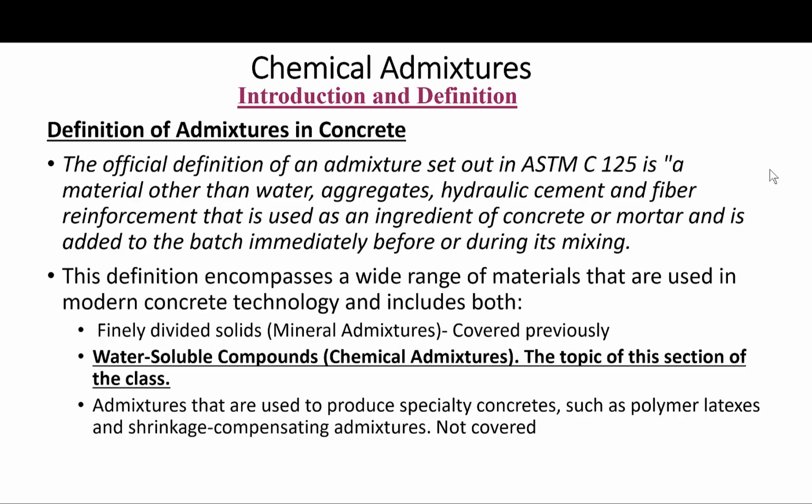There are also other admixtures that are used to produce specialty concretes, such as polymer latexes and shrinkage compensating admixtures. Those will not be covered in this class, but they are mentioned here for reference for whoever wants to get more information about them. Again, this part of the class is devoted to water-soluble admixtures that are added as solutions during mixing.